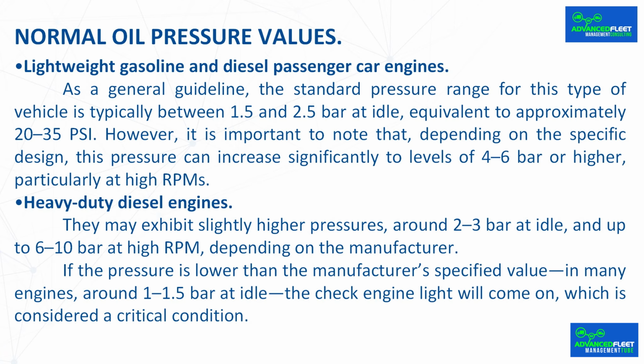Heavy-duty diesel engines. They may exhibit slightly higher pressures, around 2-3 bar at idle, and up to 6-10 bars at high RPM depending on the manufacturer.